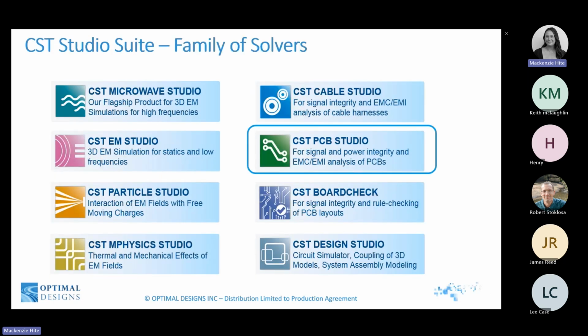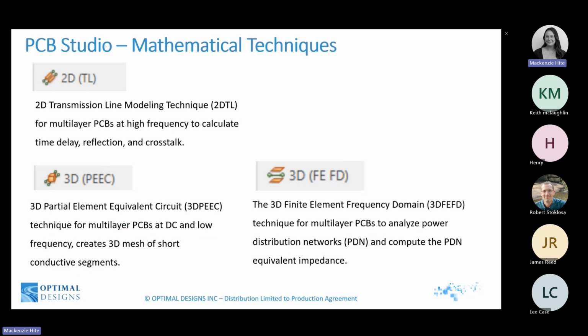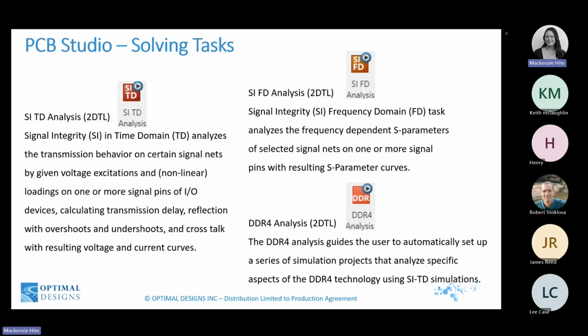Next, PCB Studio. PCB Studio incorporates 3 mathematical techniques, including 2D transmission line, 3D partial element equivalent circuit, and 3D finite element frequency domain. PCB Studio has a total of 5 solving tasks, and here we will discuss the high frequency analysis.